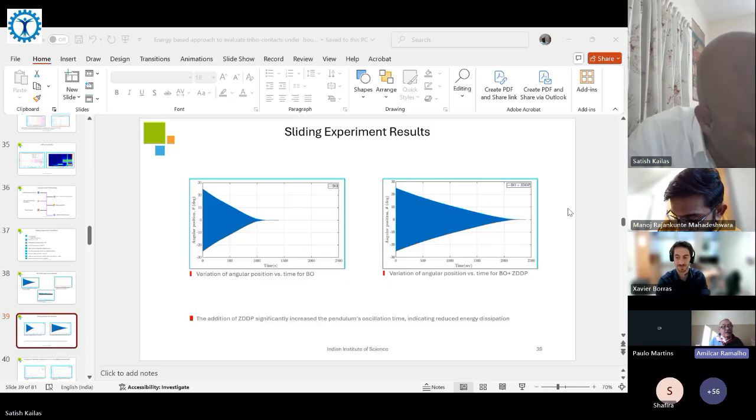In that equation, of course, we have two sources of energy dissipation. One is the damping, and usually systems work well because they are subcritical damping systems. The other is the friction itself. And we can control the total energy of the system in order to change the sensitivity of the system to measure the smallest or highest friction.